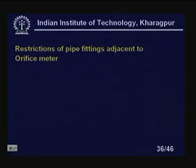Now, restrictions of the pipe fittings adjacent to the orifice meter. This is another most important thing practicing engineers must follow. There cannot be pipe fittings, pipe bends, tees, valves, etc., very near to the orifice, both upstream and downstream. What are those? Let us look at the details.